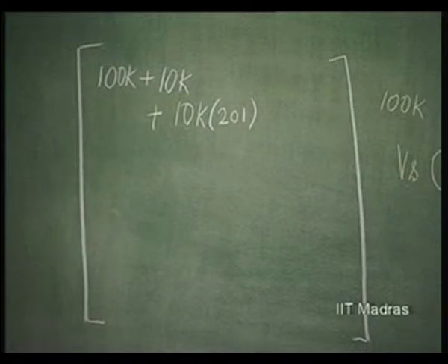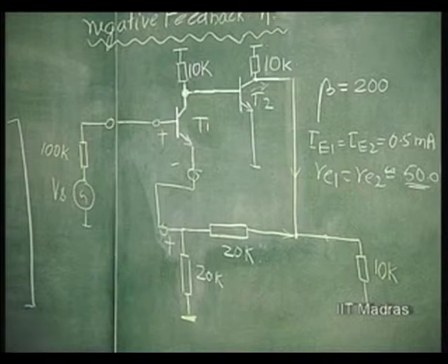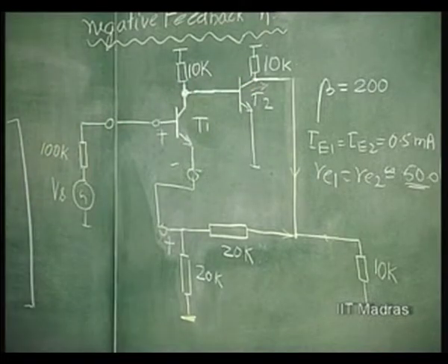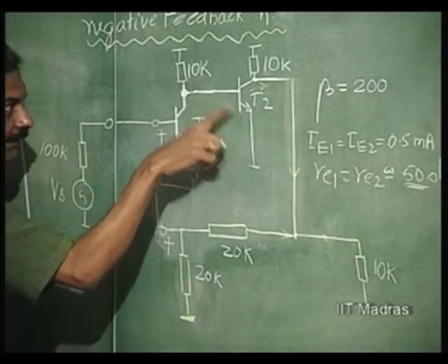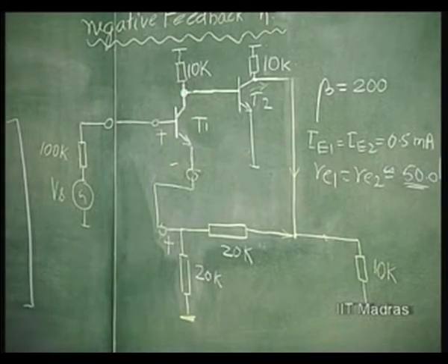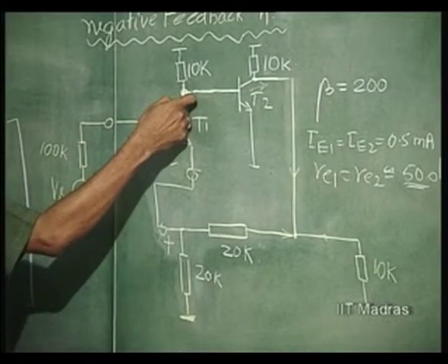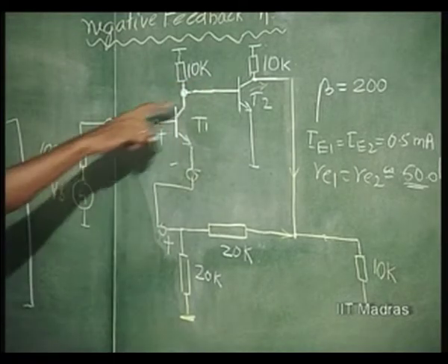So, we have here now again current gain equal to beta 200, another beta here 200 squared, and this being short circuited, it will go there. Here there is a current division, this is 10k and this is 10k. So, current division is by half. The current here, which is beta times II, is going to split between this and this equally, because the input resistance is 10k.